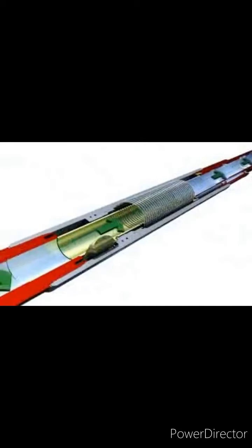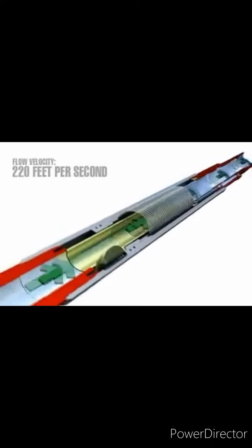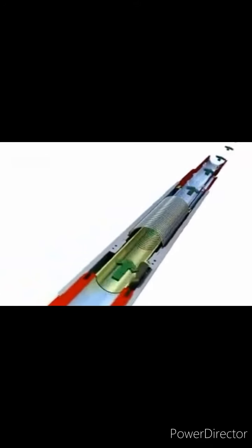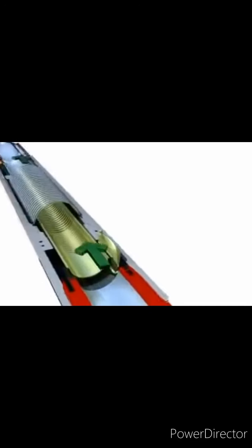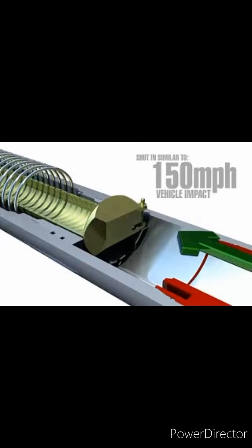We're repeating the scenario, but this time with an SSSV installed as a part of the completion at 300 feet below the seabed. The wellhead is damaged and the gas and oil go up. The subsurface safety valve is activated to shut in, and oil pressure accumulates below the flapper.